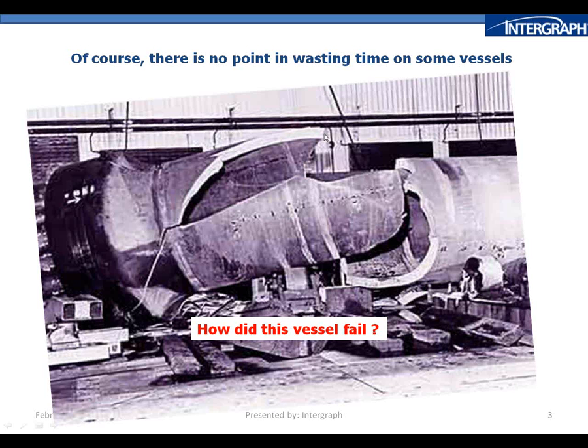Sometimes shoddy work is the thing that we have to encounter. Now, anybody who knows anything about welding will know that this welding really is a very, very poor specimen indeed. There's underfill there. It's badly done. This is obviously a manual weld.